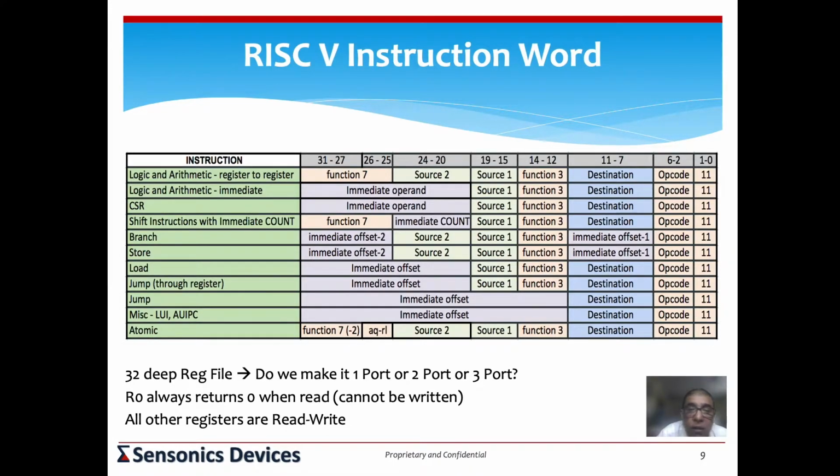You could have a second operand that is an immediate operand. In fact, they recommend you use the add immediate as the opcode, configured with R0 as one of the sources, immediate will be another 0, and destination is also R0. So there are many such things. In addition to that, RISC-V also has, interestingly, a mechanism by which you can add the pseudo instructions that are not defined. These are all there in volume 1 of the document.